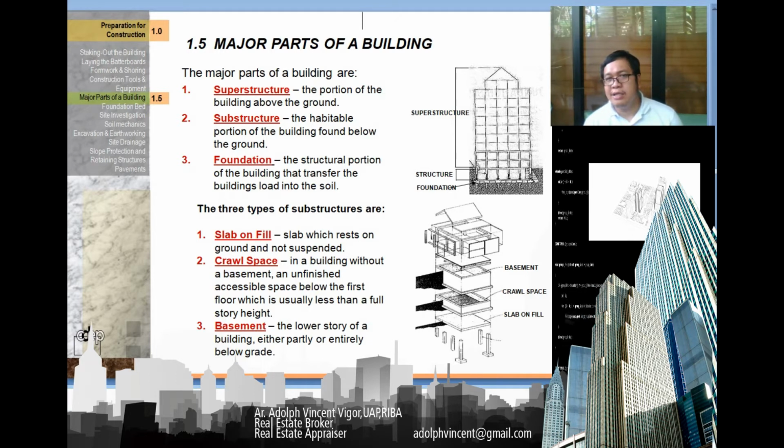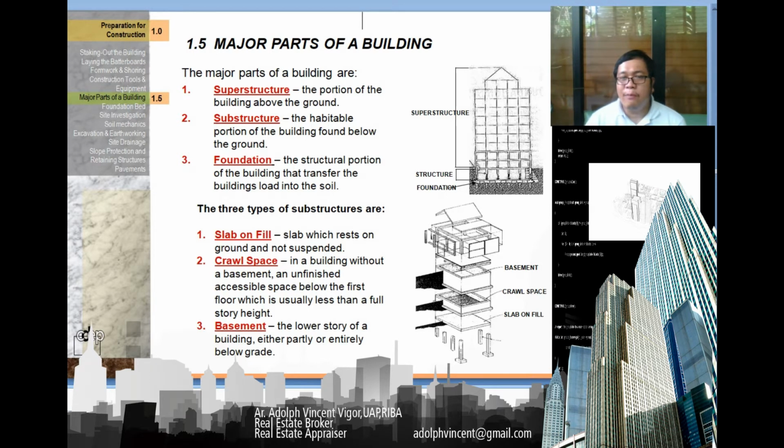Then we have what you call the foundation. This is the structural portion of the building that transfers the building load into the soil. When you say building load, that's the total weight of the building: the weight of the concrete used, the weight of the steel reinforcement used, the weight of the moving people, the moving loads within the building, also including the machineries and other stuff.